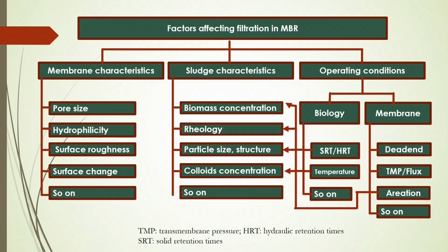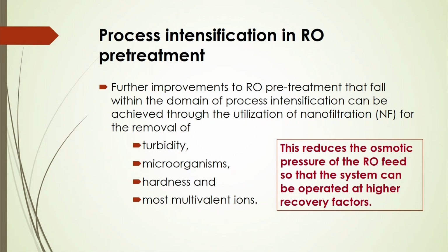So, there are several aspects where you can intensify the process. Of course, it is under research that you can intensify the conventional process based on pore size, hydrophilicity, surface roughness, surface charge, and also some other rheological characteristics, colloid concentrations, even other materials based on which these membranes are procured. In that case, this membrane bioreactor is also being used for post treatment as well as pre treatment, and